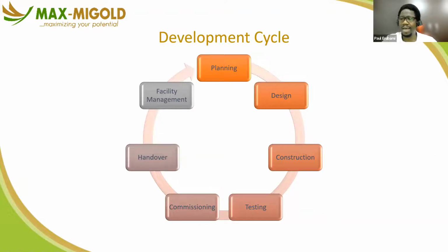So you don't have commissioning data at the beginning. You can use continuous commissioning to gather data over the useful life of the assets. At the handover stage, like I said before, you are receiving a set of drawings, a set of documents, information and transcripts of transactions that took place during construction, minutes of meetings, communications, approvals for changes, documentation of those changes, snag lists, you know, so many things that need to be done and handed over to you. We're going to be looking at quite a bunch of these in today's class, right? So these are the things that come to you as handover.